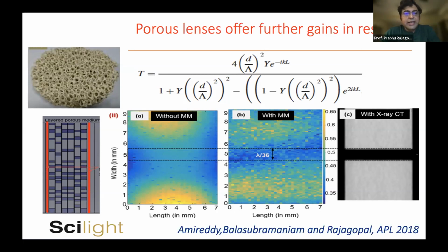Yeah. So in a concrete structure, for example, what they want is strength typically, and that strength is correlated with wave velocity. So what we do is we send sound across the bridge, and then we measure the wave velocity in transmission. And if the wave velocity is 4,000 or 3,000 meters per second, for example, there are lookup tables by which we can predict the strength of the cement and whether it is set properly. I was coming to something else. That is, you are seeing the cement, you are seeing the concrete, but you are also developing a crack. That is what your resolution is going to tell us about. And the crack is because of some chemical changes, some minor things, some impurities, defects, whatever. Is there some greater insights there?